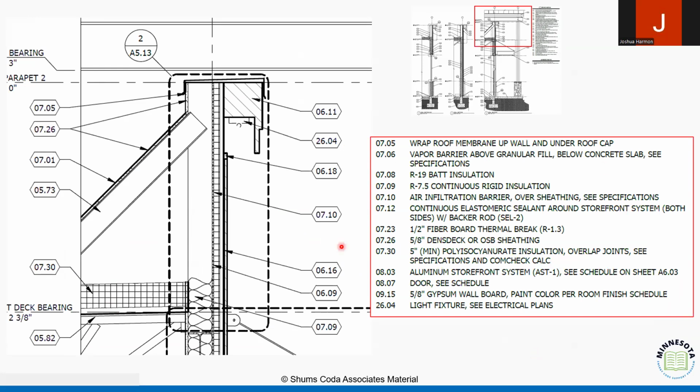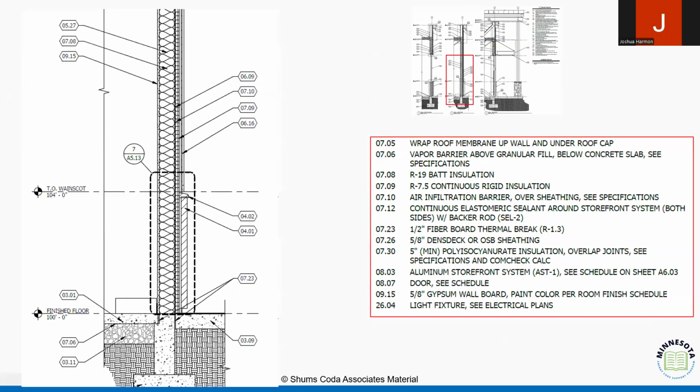And one of the things that is interesting is there's even insulation that's not identified in our COMcheck that we could calculate, right, for the fiberboard insulation for the thermal break? It's R1.3, but again, it could have an impact. But we're not even incorporating it in that design. Another example here is I'm going through those systems and saying, okay, do all of my wall values comply with the design in my COMcheck?